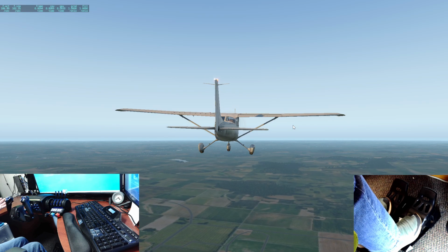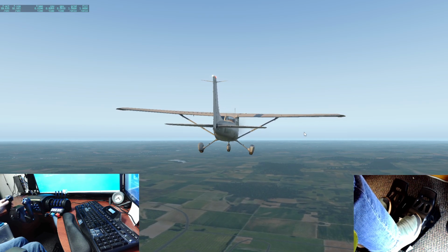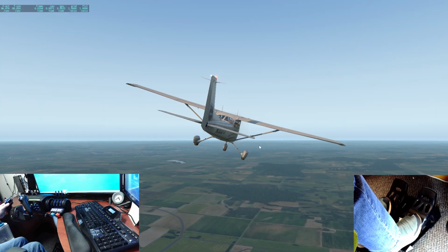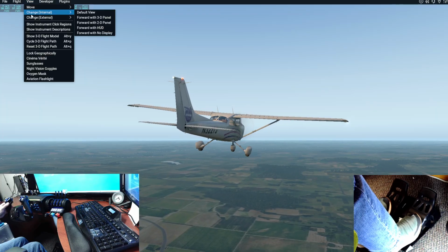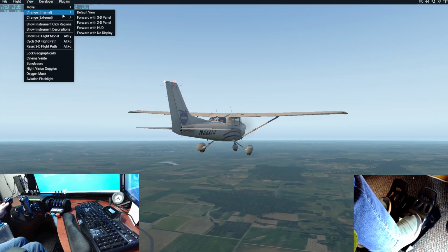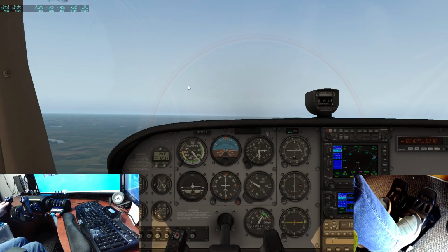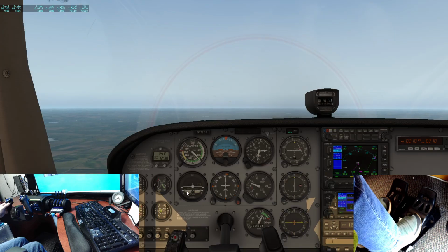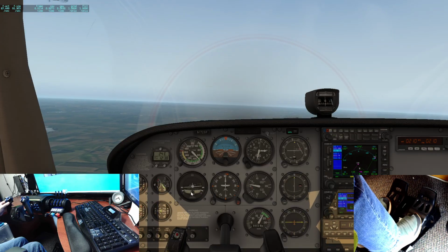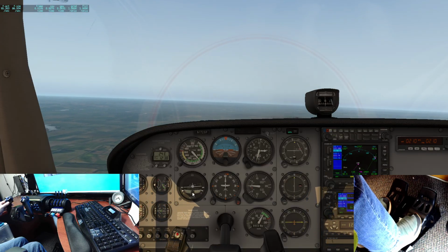So why do we have to have a rudder in the air? I mean, why can't I just do a turn like this? Well, if we go back into the cockpit, let's go in here. Okay, so you're going to notice your turn coordinator. There's a little tiny ball. This works just like a level that you use for construction or building something to make sure something's level. It's just a curved tube with a ball in the center of it.